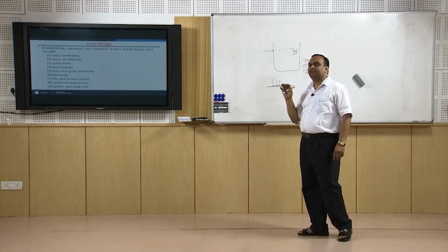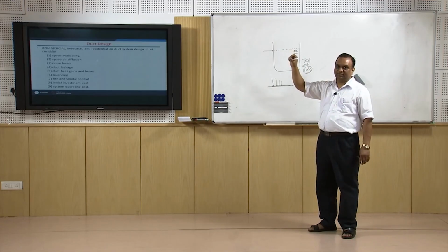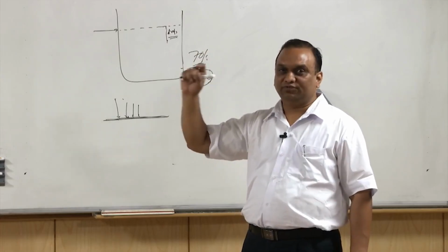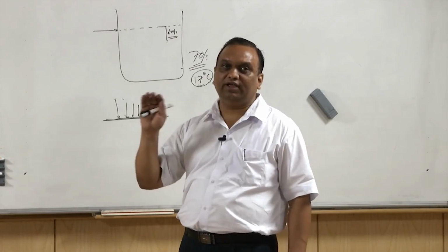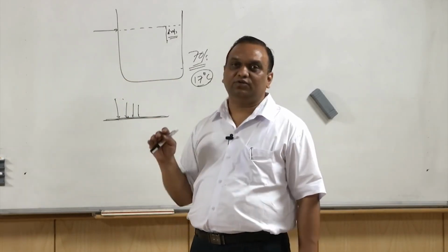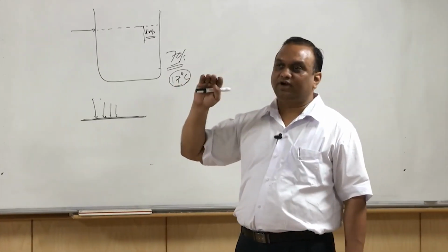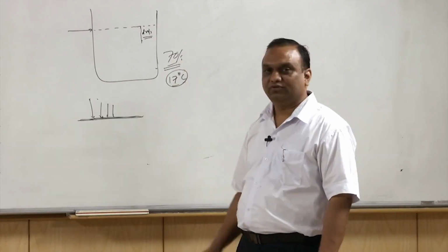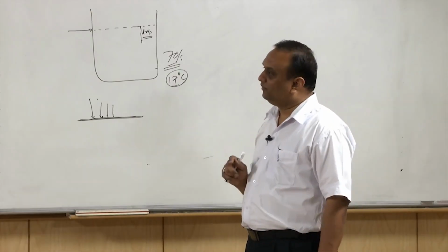You must have seen in some of the buildings discolored walls in the vicinity of the duct. That is due to sweating of the duct. The ducts were not properly insulated. That is why when the hot and humid air came into contact with the duct, condensation took place, and the water vapor condensed on the duct surface, subsequently it discolored the wall. So, you must have observed such things in many of the buildings.